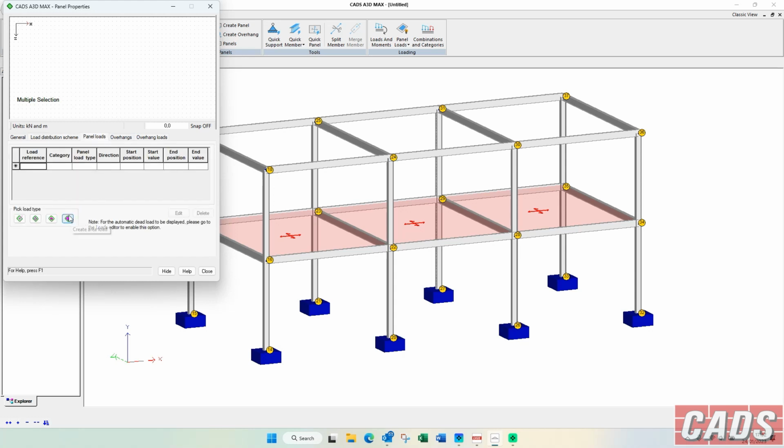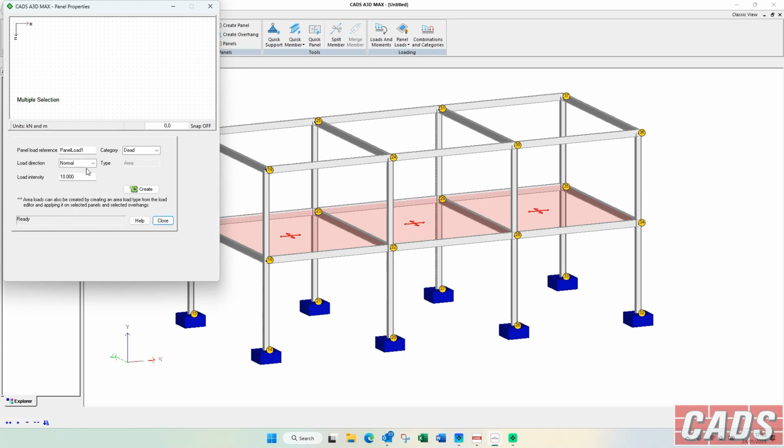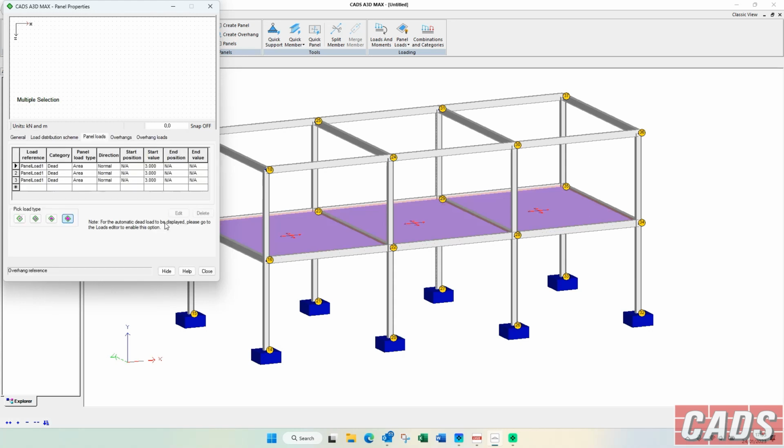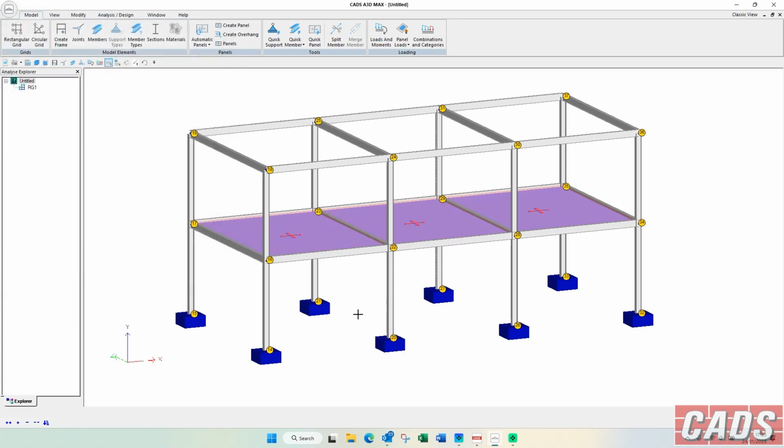And you can put panel loads in. So they can be quite complex, not just uniform. You've got create point load, line load, patch load. All you do is choose your type of load, what the value is, and say create and close. What happens then is when you run this, it will distribute that uniform load to the trapezoids, and you'll see that on the frame.